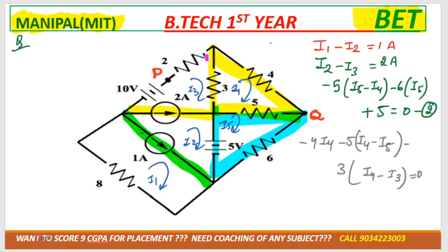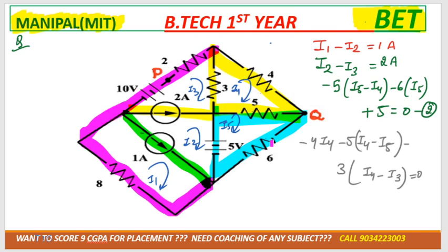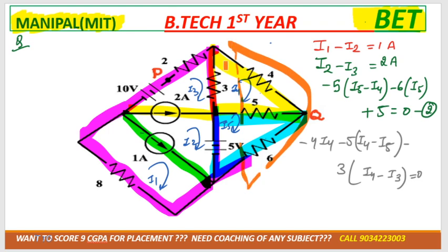How will we get it? Through the super mesh. Suppose you are standing here, you need to move. You can't follow the path where a current source is present, so you can move through the outer path, or you can move through the inner path, diagonally. Now students ask, ma'am, can we take this one also as the super mesh? The answer is no. A super mesh condition arises when there is a current source in between.